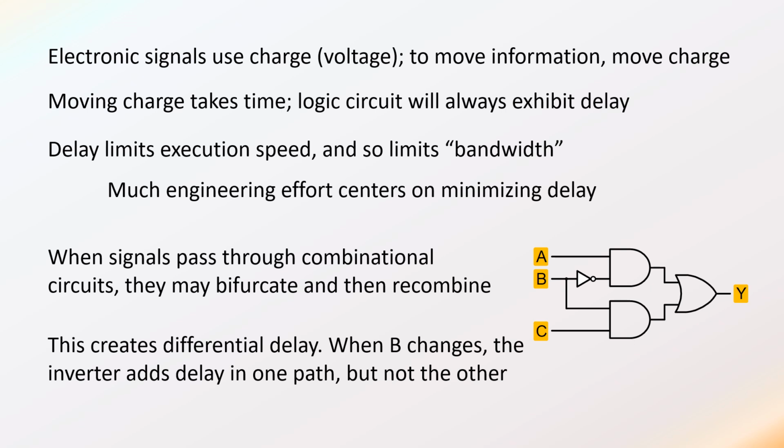So if we want to minimize the amount of delay, we can do certain things. We can make the transistors have less resistance when they're on. We can make smaller circuits so there's less capacitance to drive. And that's about it really. We can come up with ways to just move current more quickly around the internal nodes of a circuit.